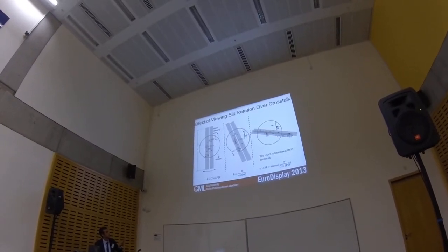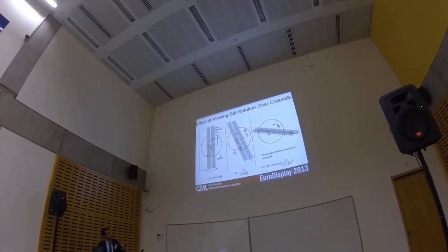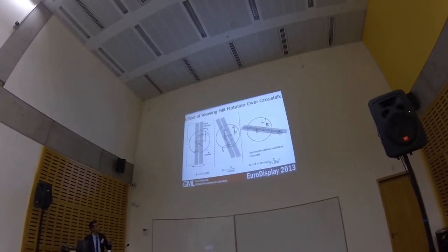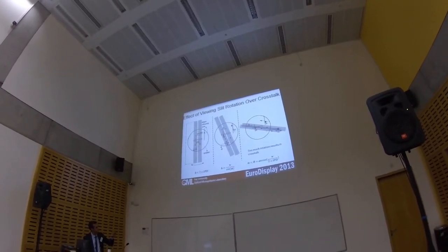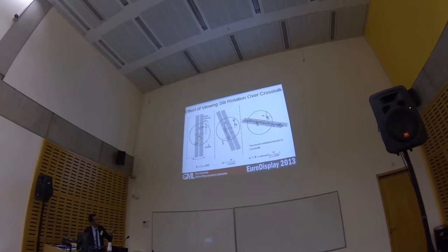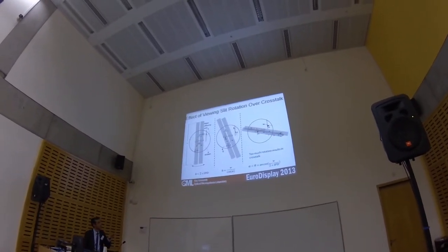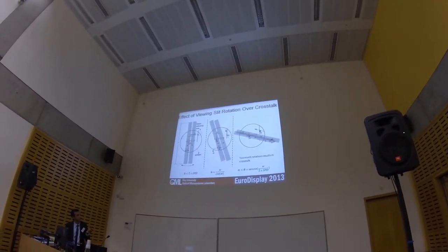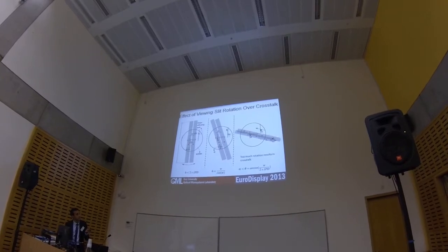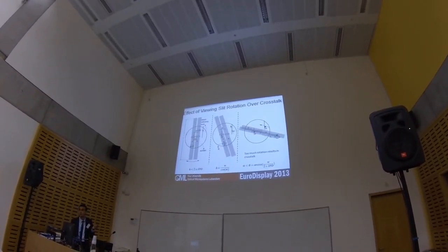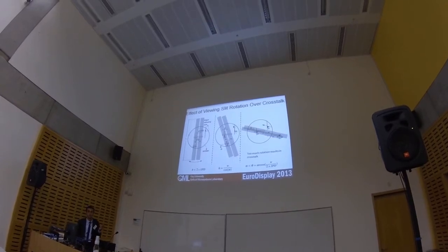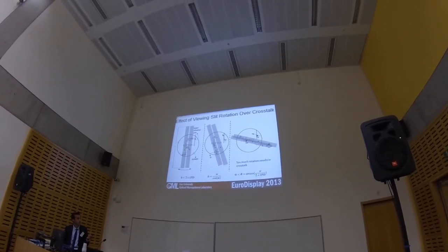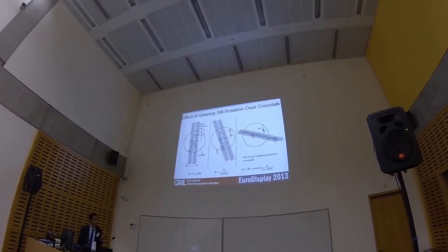When we rotate the screen, the actual width omega doesn't change, but the horizontal width, h, changes, with a relation like h equals omega over cosine alpha. So when it rotates too much, it results in crosstalk, because h would be greater than 2 IPD, 2 interpupillary distance, so the image for one eye will leak to the other eye. We have a maximum rotation angle of arccos of omega over 2 IPD.